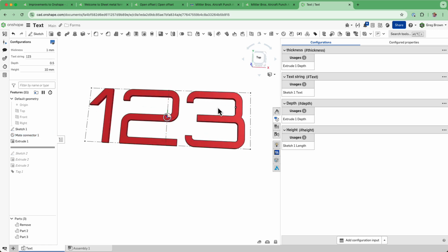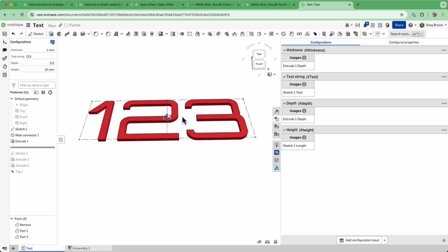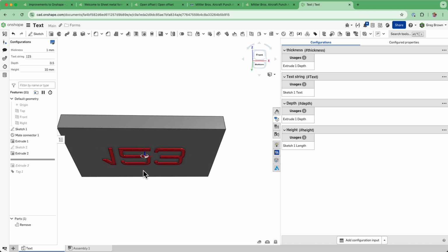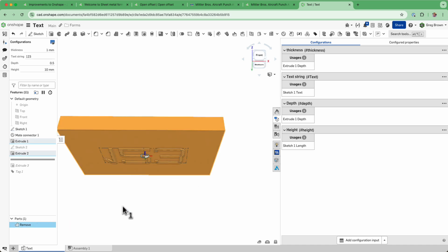I want to do this centered, so I've just created a center line here. And we couldn't use this, sorry, because there are 3 separate bodies and we can only use one body when we do a removal tool. So what I did was the obvious, which is just block it over the top and create a single body of it.